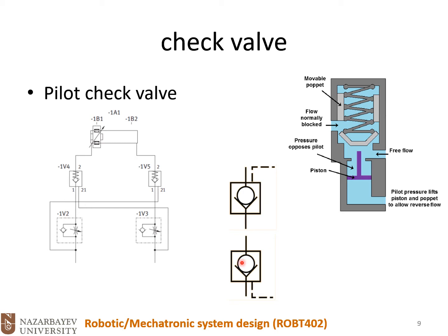We have this type. Now the air could flow freely both ways. Once the signal is stopped or this line is closed, this small piston will retreat back, and now this obstacle will work as a non-return valve, like the ball in the symbol.